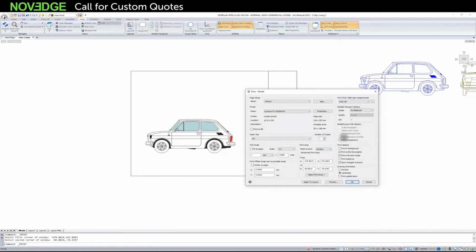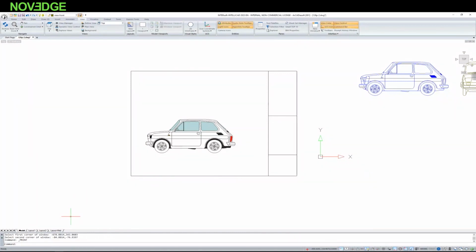Sometimes you define transparency to a layer. And if you have this transparency selected here, then remember that it will not be printed if you choose a print style. If you do not choose the print style, meaning the thickness and colors will be taken from the elements, then the transparency will be printed. Please note that transparency cannot be printed in the print style. However, if you select transparency and style together, the program will inform us and ask you to choose one of them. Now I'll go to the second way of printing from the program.